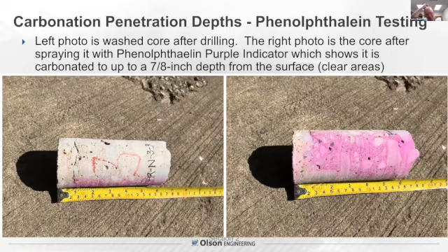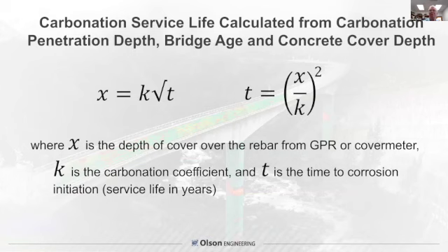And finally, the service life prediction for carbonation is done this way with the bridge age and concrete cover depth. Based on knowing the age of the bridge and the carbonation depth, you can figure out the remaining service life as well.